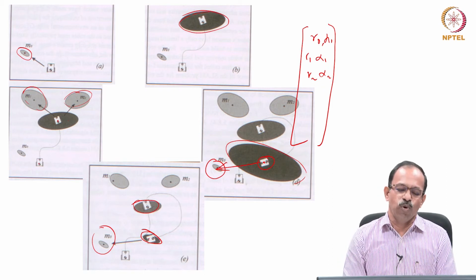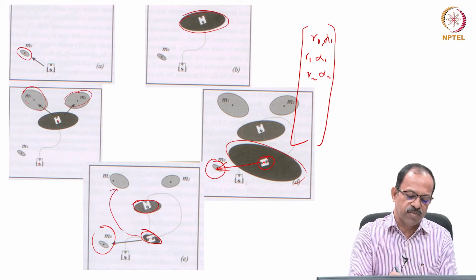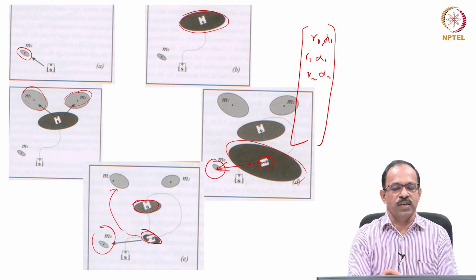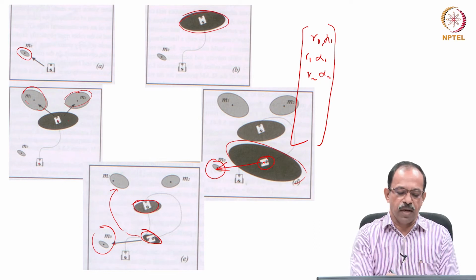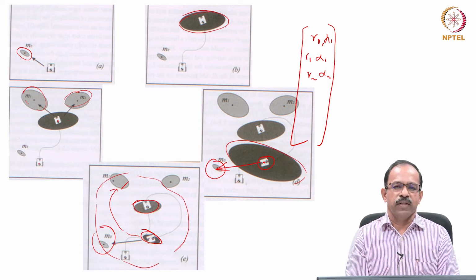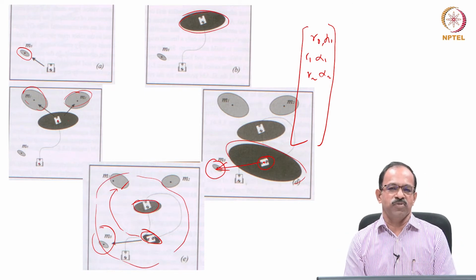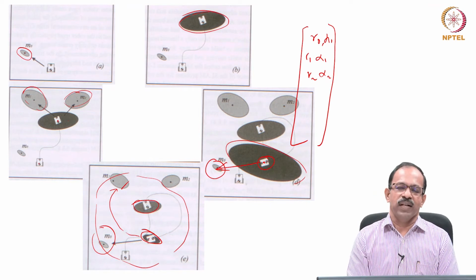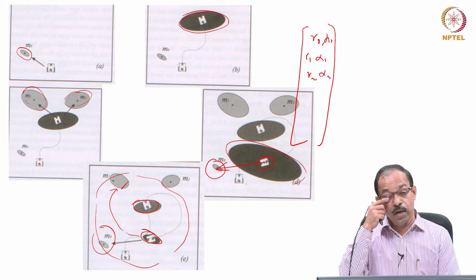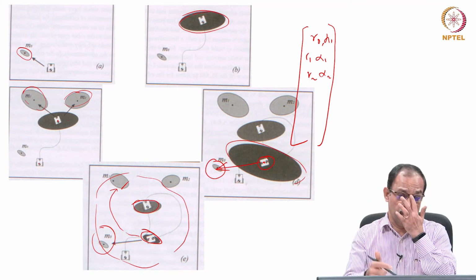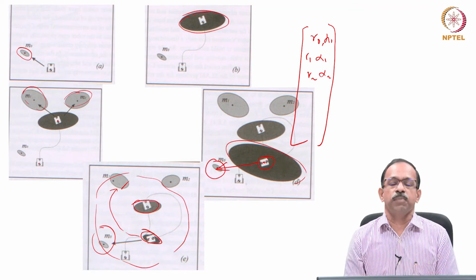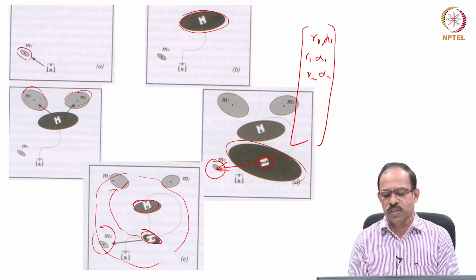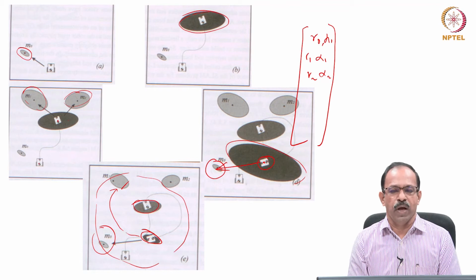Like this, the robot keeps on moving, and if it moves further from here, it will see something here. It will recalculate this position and record the position of the new object based on the information. After going through this many times, the robot will have much more clarity on all the objects in the arena. So it will be creating a much better map, and then it will be able to localize itself using the fusion method or the algorithms that we already use for localization. So this is the basic principle of SLAM, which only explains the logic of using the SLAM algorithm for getting the map and localization.